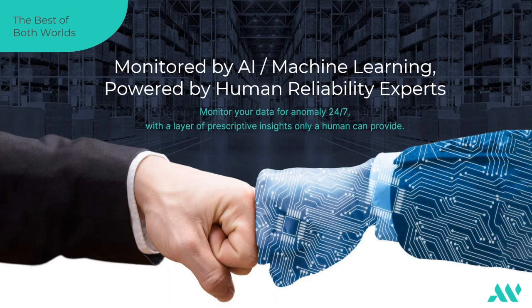One of my favorite examples of this is we were working with a company and we were talking to the maintenance manager. We're doing a year-end review and realized in 2022 they went through the same exact coupling 8 times in 1 year. Wild. And yes, the AI and the machine learning could easily point out to them, hey, you're having a coupling issue. We recommend you doing X, Y, and Z, fixing it, switching it out. But what they weren't able to figure out, that one of our human CMEs were actually able to figure out, is they started talking to the maintenance manager and found out, hey, we don't believe in laser alignment, only straight edge alignment. Well, shoot, right there's already a big problem, right?